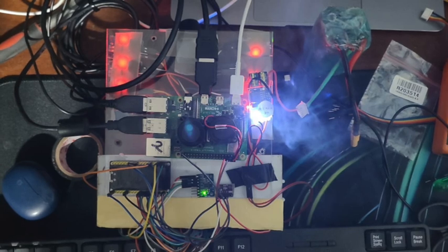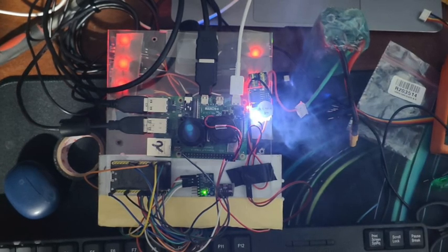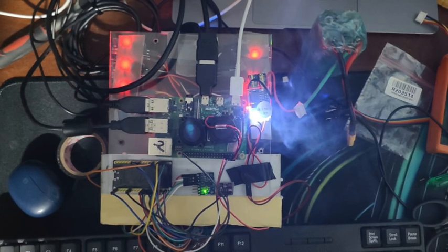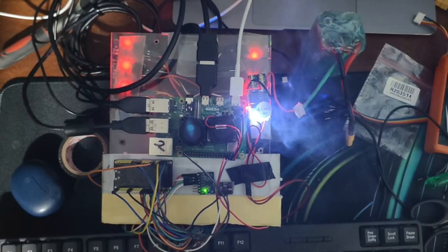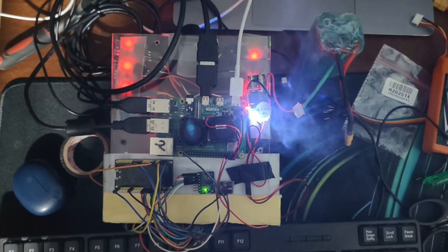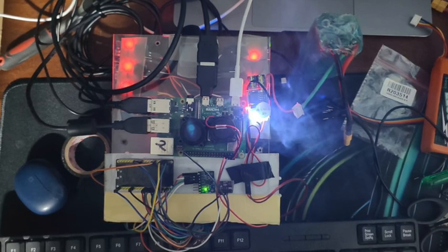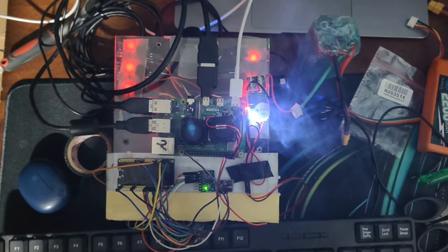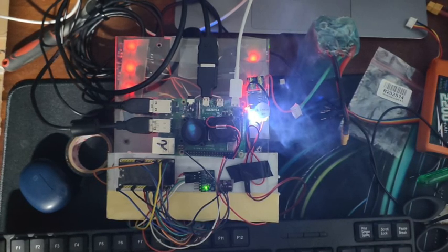All these sensors are connected to an ESP32 microcontroller, which continuously reads the raw sensor values. The ESP32 then packages this into a structured data packet that includes every measurement along with IMU and altitude data. This data is continuously streamed to a Raspberry Pi over a UART serial link. The Raspberry Pi acts as the main processing and visualizing brain.